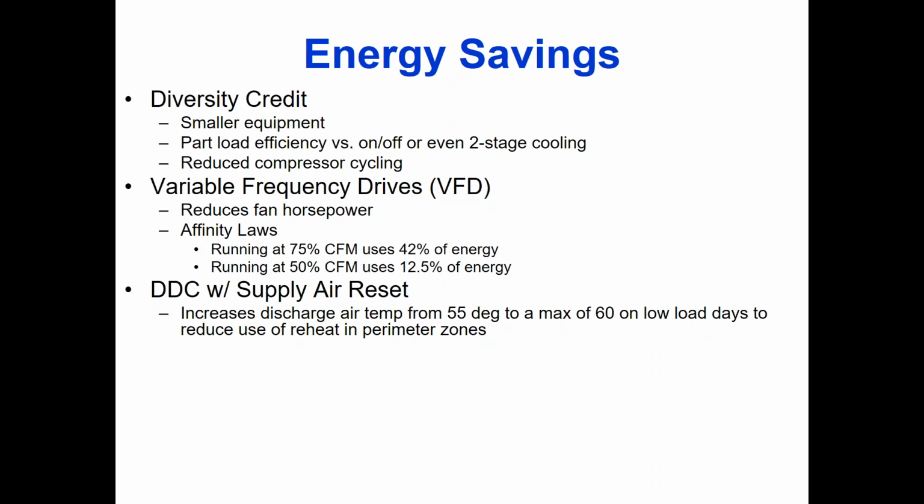But all that really means is we look at all of the zones, and if all the zone temperatures, as an average, are cooler than the set points that they want, then as an average, we're overcooling the space. So what we do is we increase the supply temperature from 55 up to 56 degrees, or 57.2 degrees, or whatever our controller calculates. And we set it up slightly, and that way those zones don't need quite as much of that reheat on the perimeter that they might have otherwise needed. We help the zones that are getting a little bit overcooled by the 55, and we reduce some of the extra heating capacity needed for the reheat.